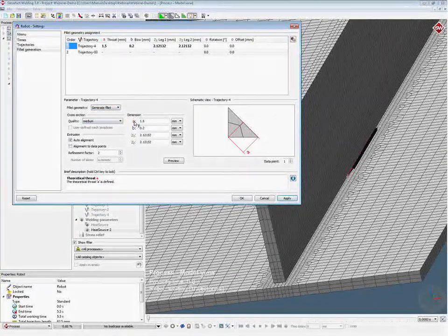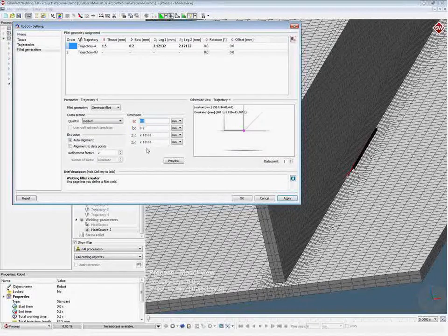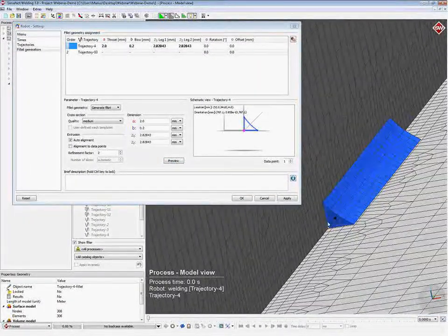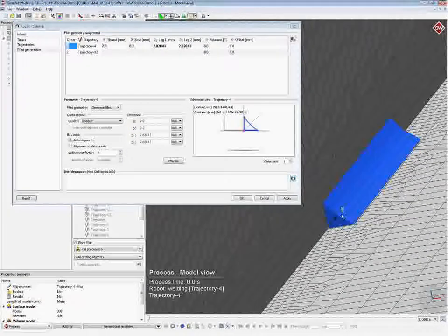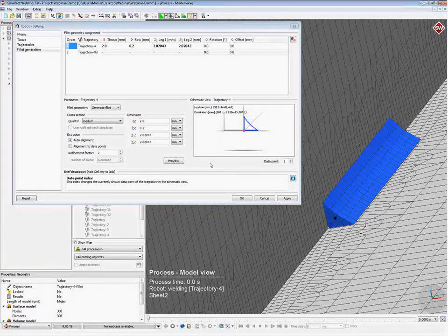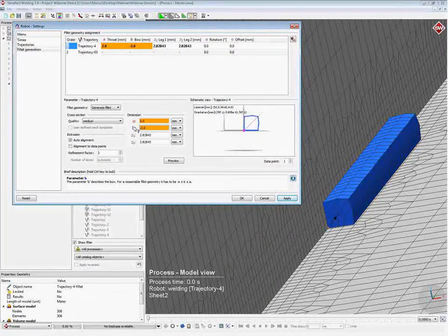two-dimensional templates that look like this, and they are very flexible. So, for instance, when we want to have an A value of 2, you can see there is this two-dimensional template which is swept along the trajectory line. And this works also very good for curved trajectories, not only for straight trajectories. And it's a very easy way to add in your filler material. You can also change, for instance, the curvature, whatever.